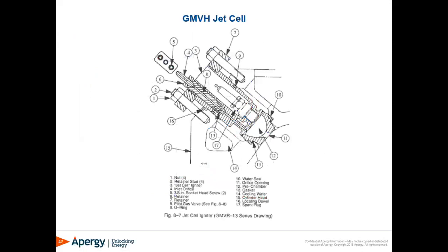As the piston moves down towards BDC, the check valve will open and release fuel. Then as the piston moves up towards TDC, it compresses the air and fuel mixture in the cylinder. Once the pressure is high enough, the valve will close. The port has been specifically designed to help move the flame front through the cylinder to ignite that lean mixture.